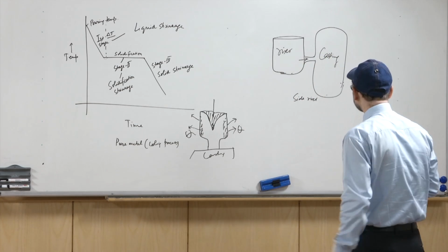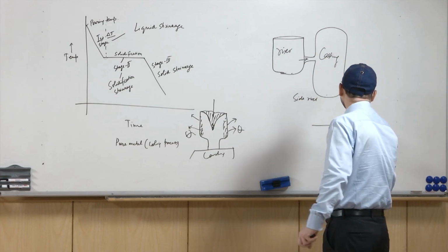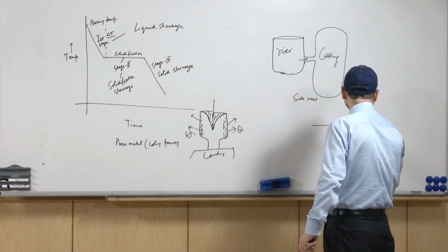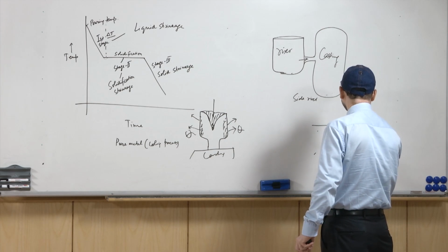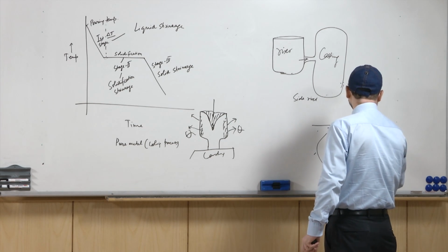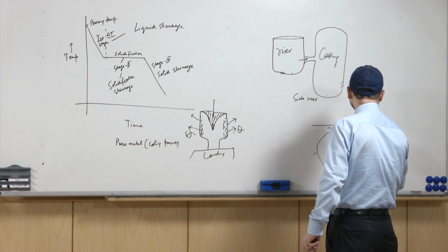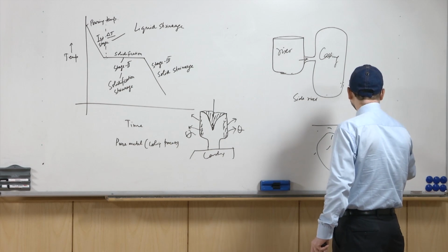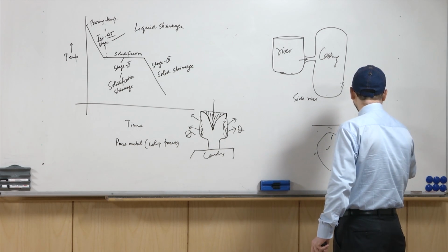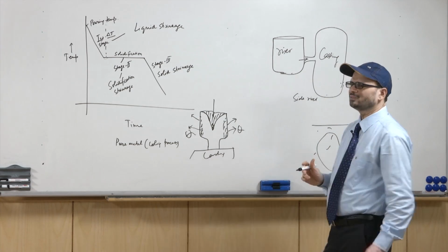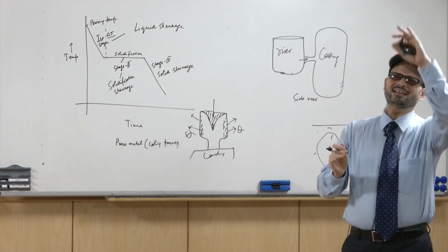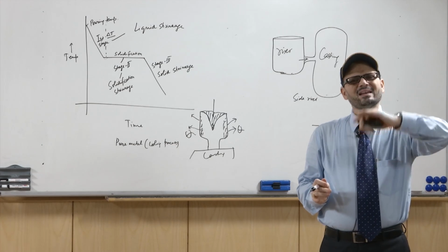So, in that case, when we have a blind riser attached to some casting, what we do is provide some core inserts so that it is open to the atmosphere and the atmospheric pressure still acts.